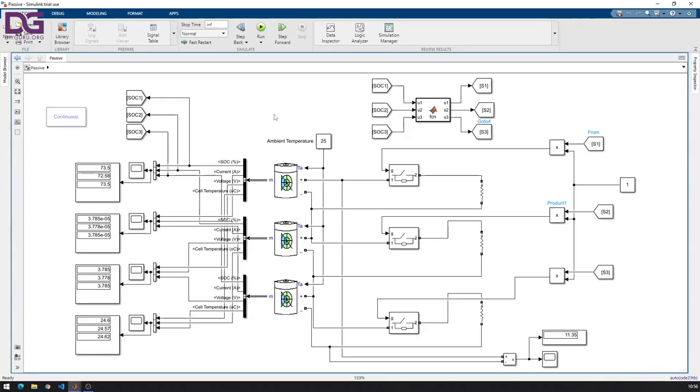If you are using heat to dissipate the energy, then the capacity of the battery pack is reducing, right? So what it effectively means is your range is dropping if you are using the cell balancing. Fortunately, cell balancing is not used every charge and discharge cycle. Depending upon the chemistry of the cells the time span will vary, but it will usually happen at the charging station.